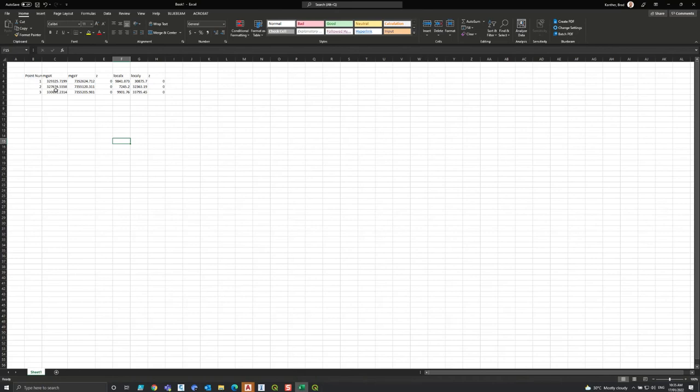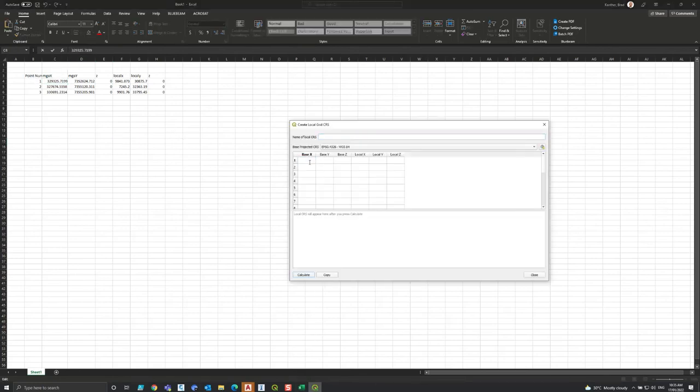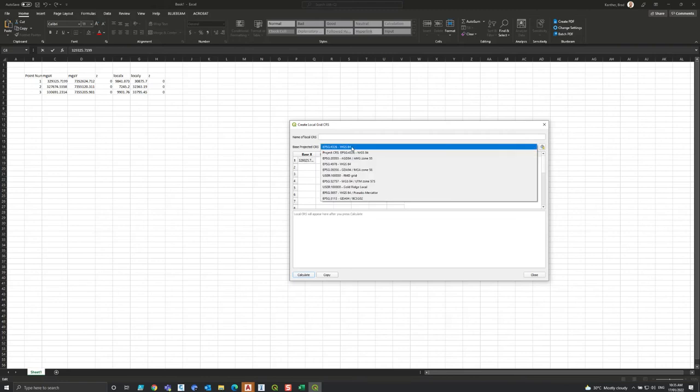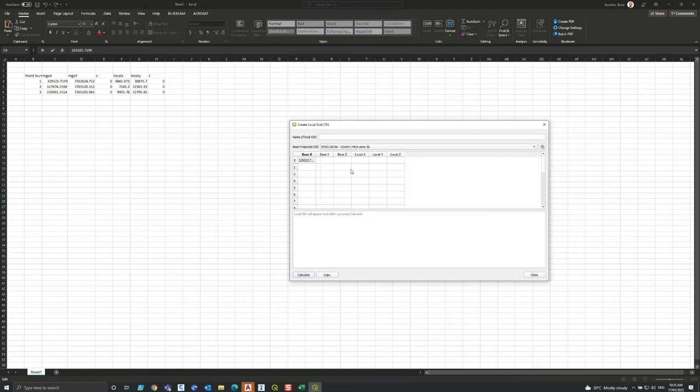And all we have to do is we have to manually, unfortunately, paste these data sets in here, because you can't just copy paste the whole lot. You've just got to go one by one. Now, just be careful. The base coordinate system has to be the known coordinate system. So actually, we should better set this now. I know it's MGA 94 zone 56.